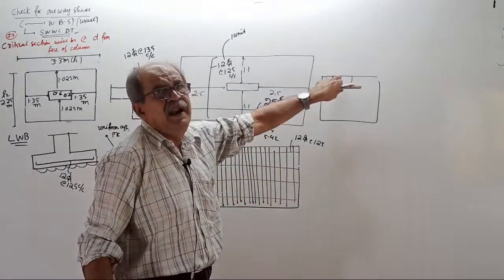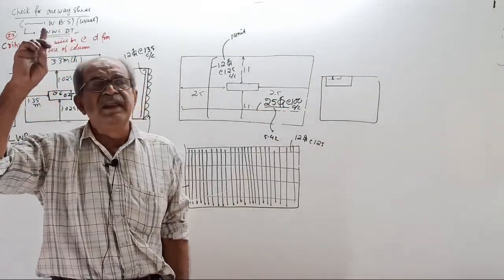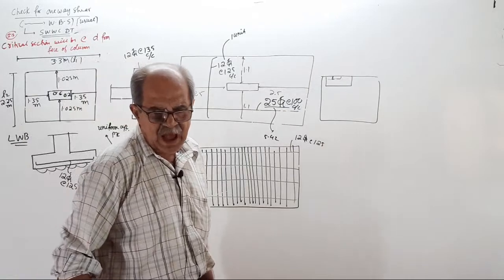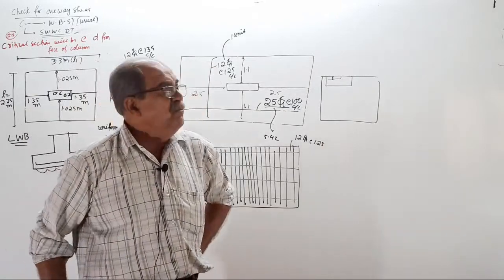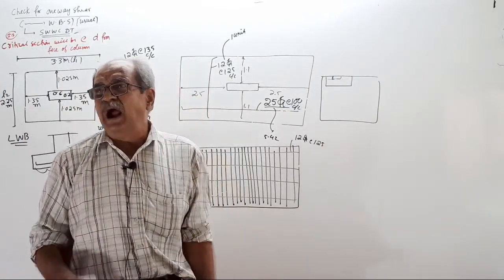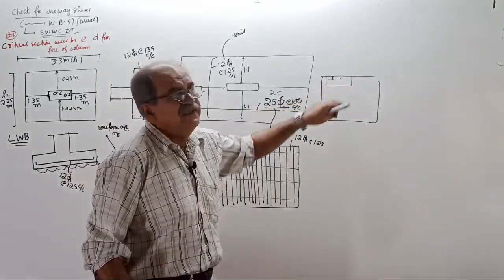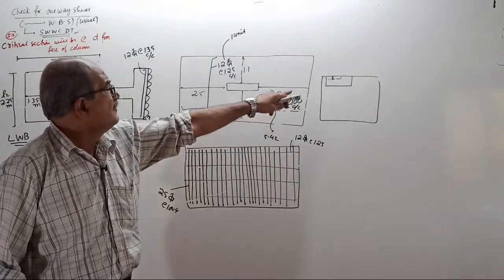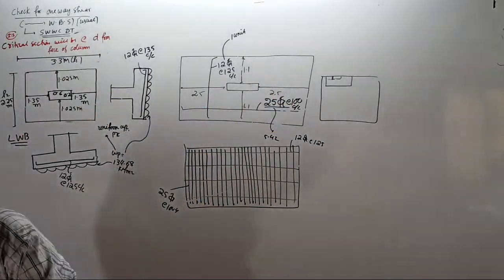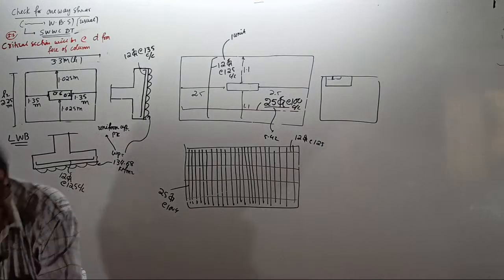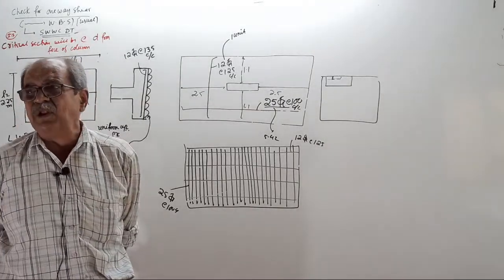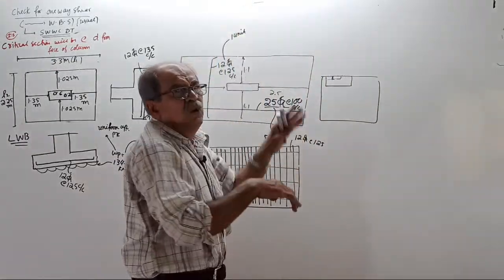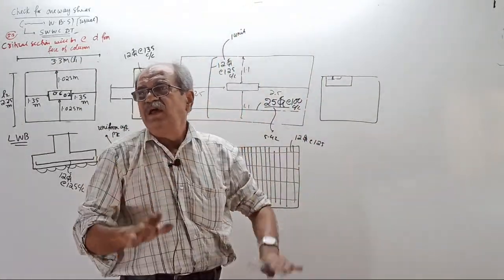Independently, they provide footing. When I was taking class in Hanumannagar area, I could see a neighbor building as I was going up and down every day. Every time I used to wonder, what is going on here? Have you seen this way? Edge column. They provide fully eccentric footing. Nowadays they will not do it because the designer will not provide. Yes, this footing will lose contact with the soil.